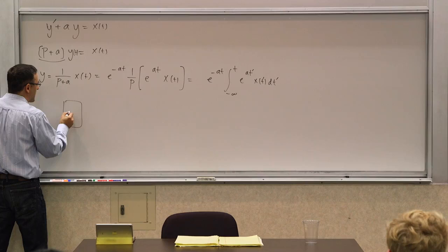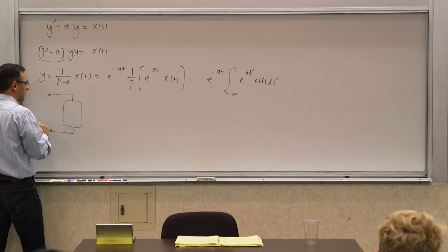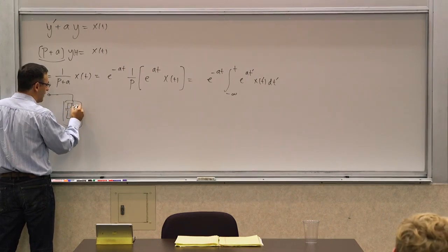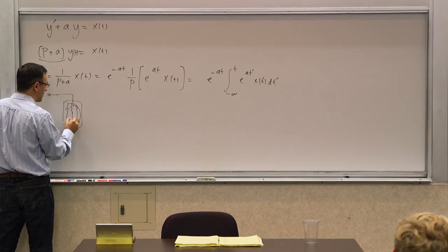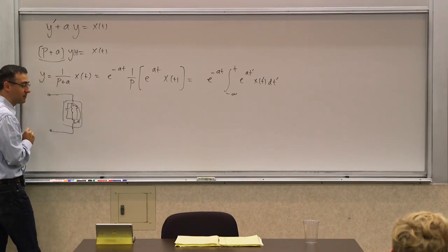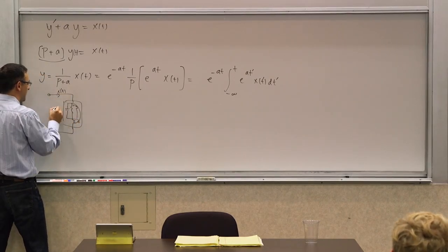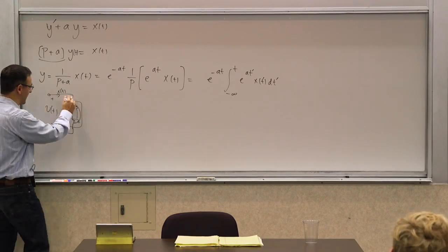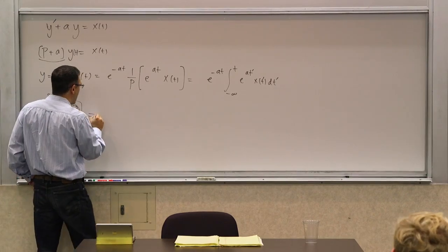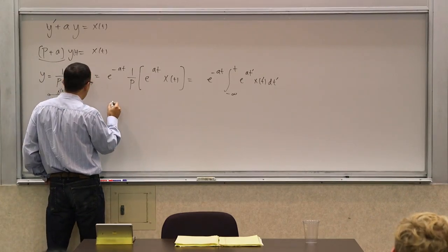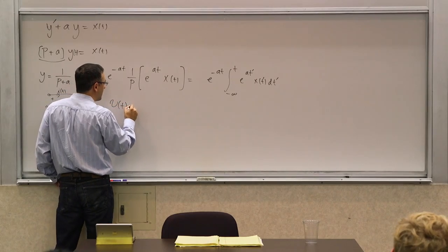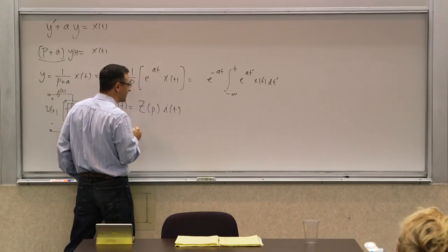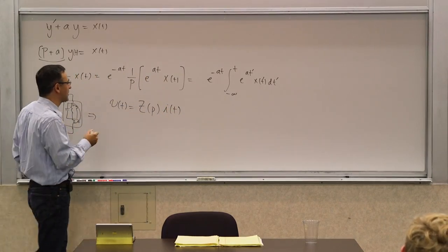In general, if you have a two-terminal thing, which may have inductors and capacitors and resistors connected in funny ways to each other, as long as you have these two terminals, there's a relationship between this current and this voltage. So it's a compound branch, made of some elements inside. As long as these are lumped elements, v of t can be calculated by applying this operator Z of p on I of t. This is what we call the impedance operator.